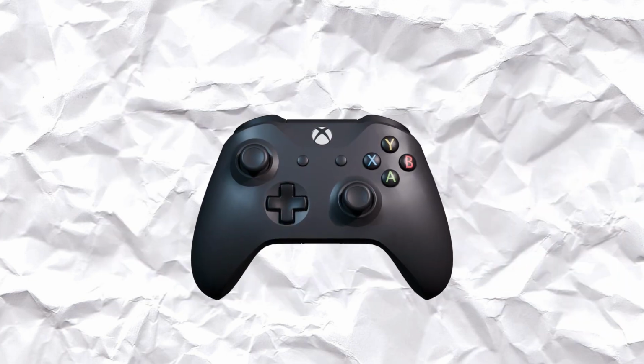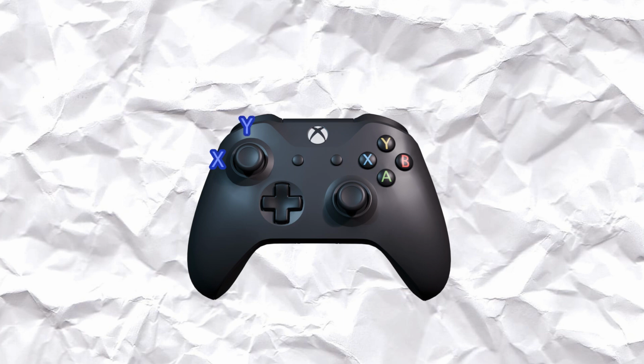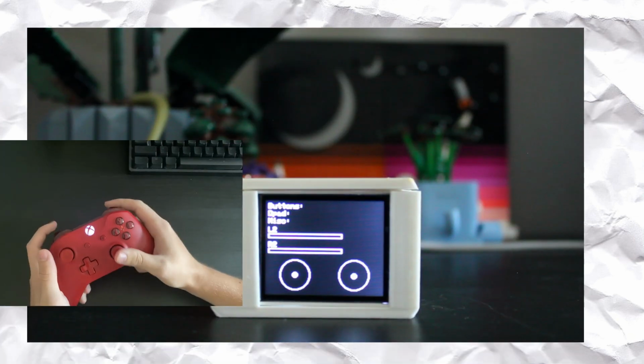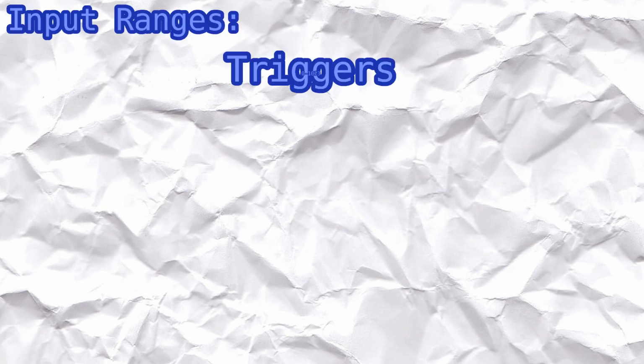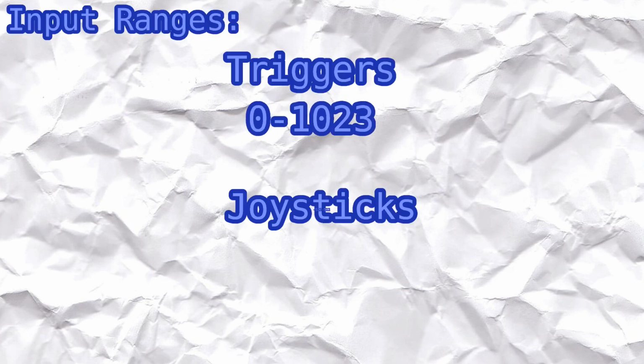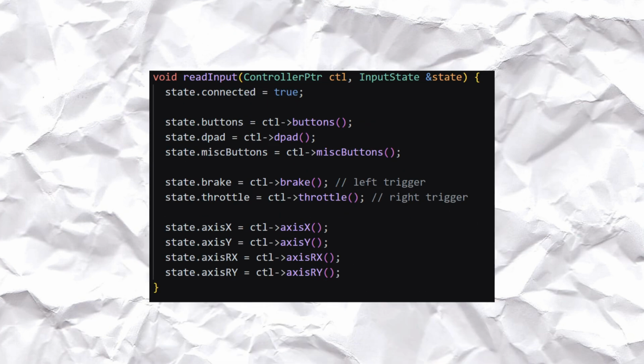Then we've got the analog stuff. Throttle, brake, and the 4 stick axes. Axis X, Axis Y, Axis RX, and Axis RY. These are all plain old integers, and that's an important distinction here. Triggers and sticks give you a value of how much, rather than a simple on or off. So instead of a bit, we get a number. Triggers roughly range from 0 to 1023, and the sticks range from -512 to 512, with the 0 being in the center. And yeah, that's the whole struct.